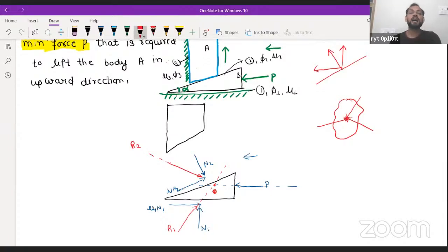If the forces are non-concurrent, then there is one more condition for the body to be in equilibrium, that the forces should be parallel. Only in these two conditions will a body be in equilibrium. Otherwise, for three forces, the body will not be in equilibrium. Apart from these two conditions, whatever the configuration of three forces is, the body will not remain in equilibrium.